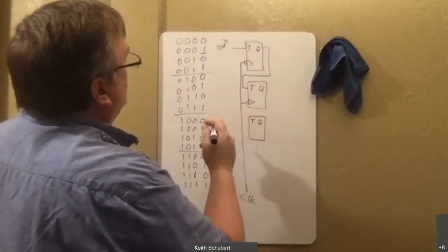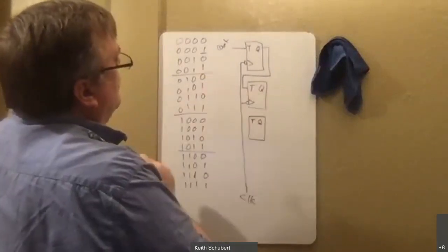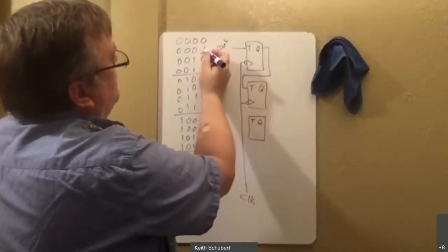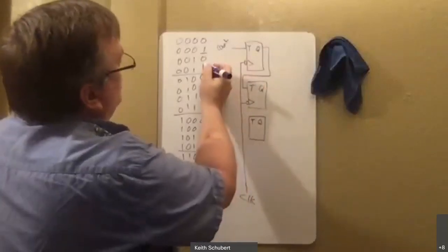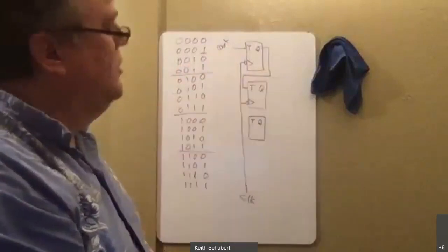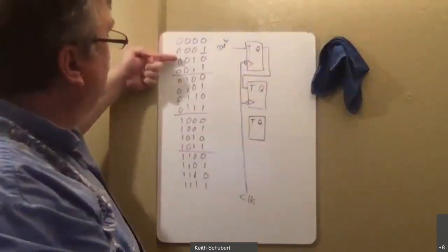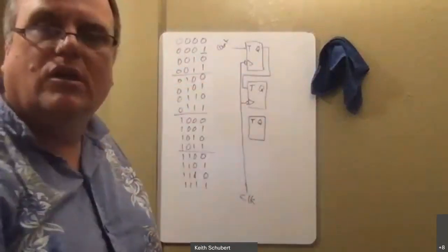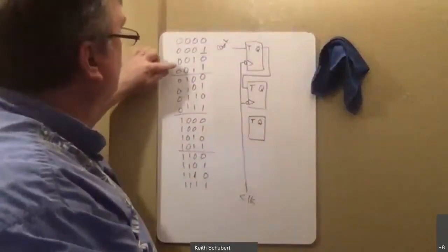Now let's take a look for our next. Actually, I should make one more category, right? I want this to go from a 1 to a 0 or a 0 to a 1. I want to count. But what if there was a bunch of held states? What if count was not on when this came in? All right. If I'm counting as fast as the clock goes, this will work. But what happens if I'm not counting as fast as the clock?